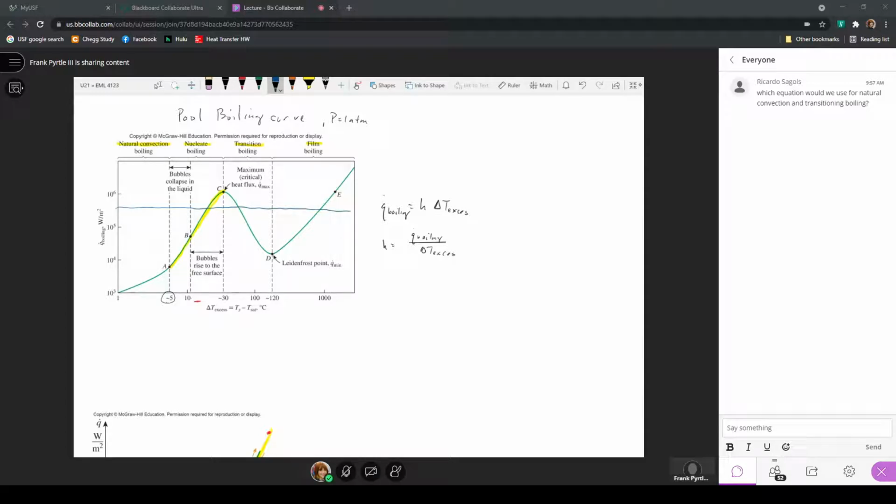again, we're not considering this transition boiling because this is not a place that you can get to with a heat flux control problem. But here, when we consider these temperatures that are associated with the surface temperature, because again, this excess temperature is just the surface temperature minus the saturation temperature, the saturation temperature would be considered a constant here. If I can get this particular heat flux at this temperature, well, it just says, as long as I have materials that don't melt at these temperatures above the saturation temperature.